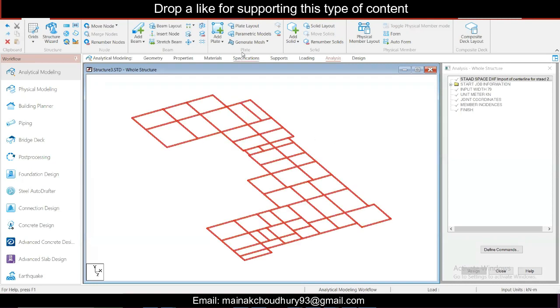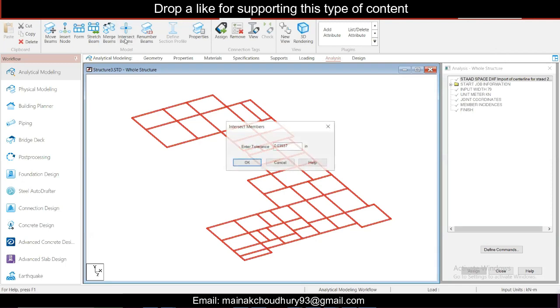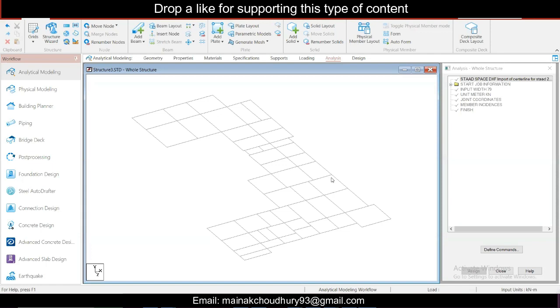So simply just select Ctrl plus A and then go to beam tools and then intersect beams and then click on OK. So you can see beams are created. Now the normal steps will be there.